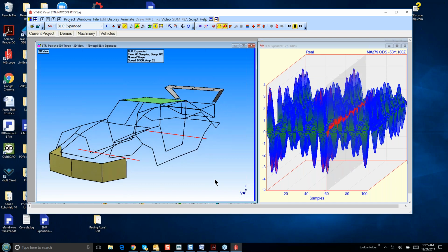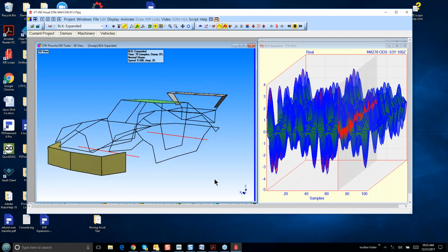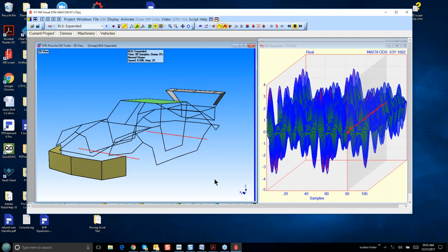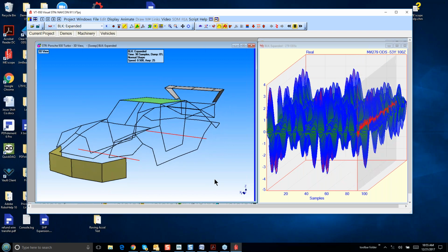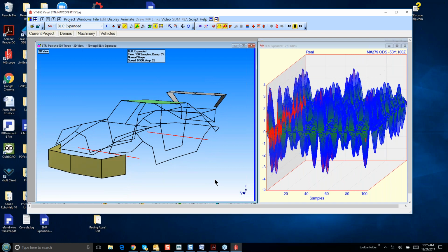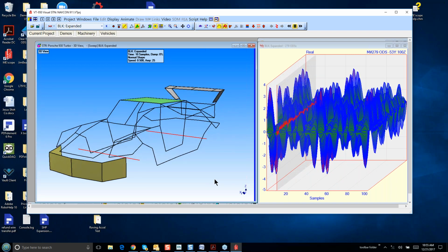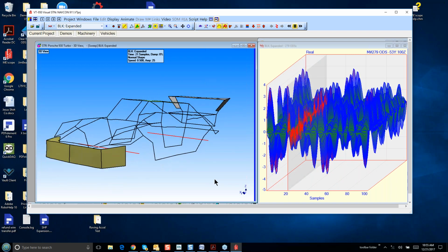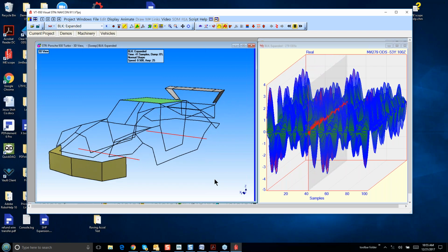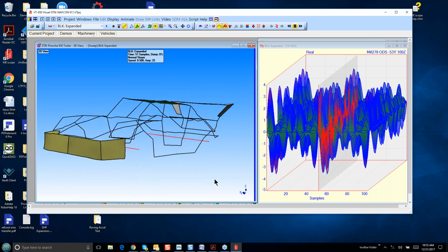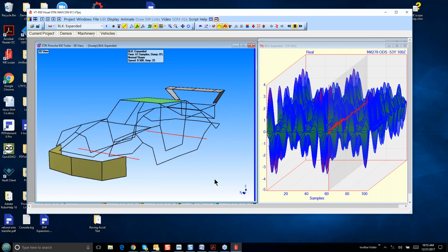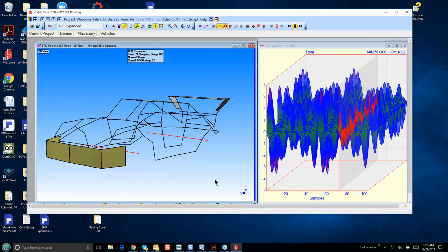Again, simulation, riding over some bumps where we're simply measuring the acceleration at 4 points on the car body and curve fitting the first 2 suspension modes of the car to the time traces.